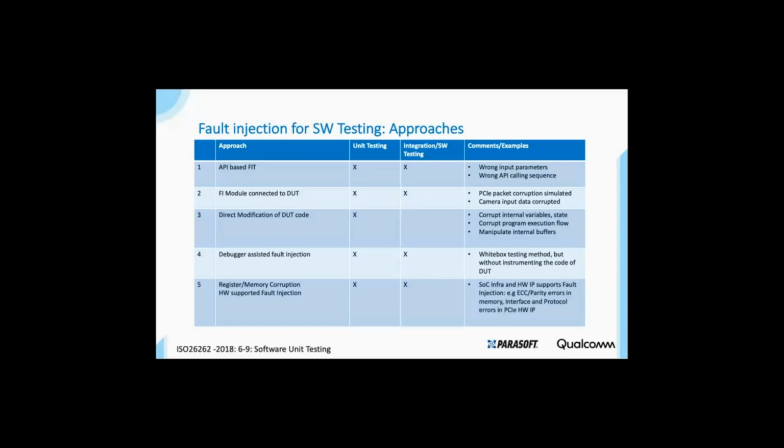But with fault injection testing, our customers showed a deep interest in being able to reproduce it themselves, which was a very good, very interesting revelation for us. So we typically don't expose a lot of these details to our customers on what kind of registers we have, due to proprietary reasons, and how you can corrupt them or give them code which is on purpose as a fault. But when we got into functional safety, we realized that our customers have to be able to trigger the same fault so that it is handled at their level at a higher application of MCU.